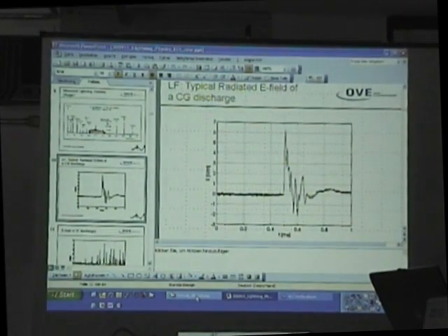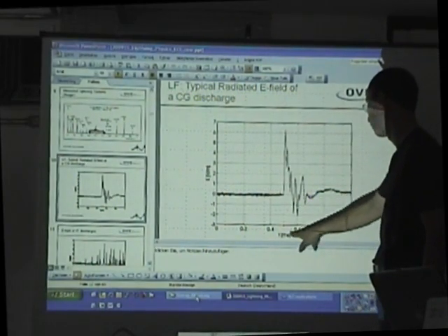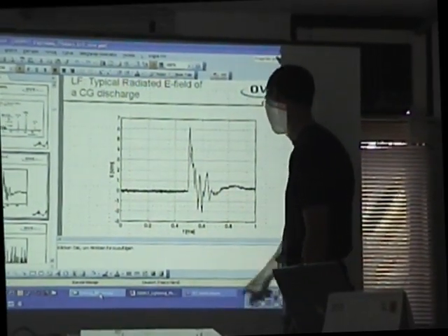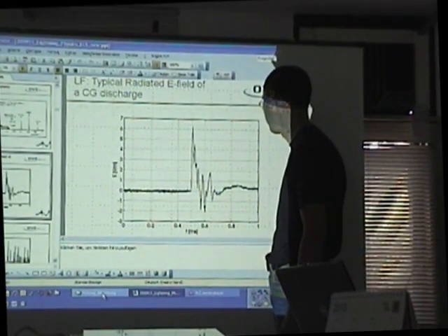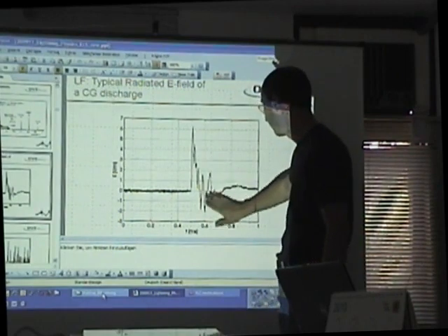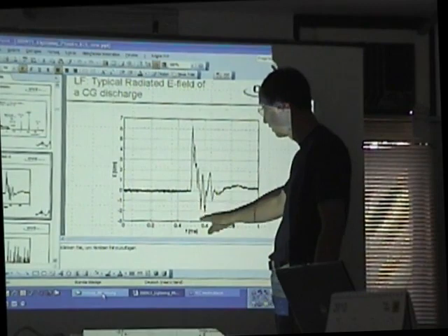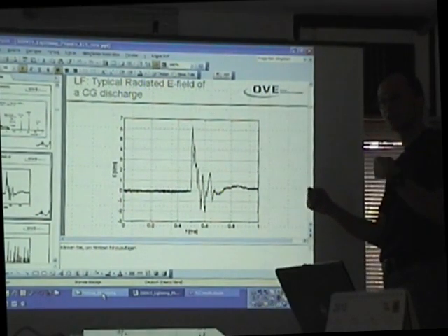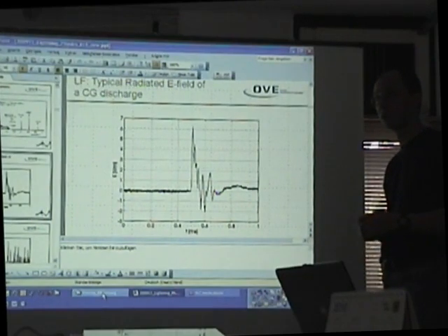What happens in fact, and this could be part of ionospheric reflection, is that this is 100 microseconds. I think it's too close. But what you see, assuming this is the ionospheric reflection, is that the ground wave is somehow damped, and the ionospheric reflection stands out. And afterwards, this ionospheric reflection is detected, and sometimes the lightning location algorithm produces two points, two locations.